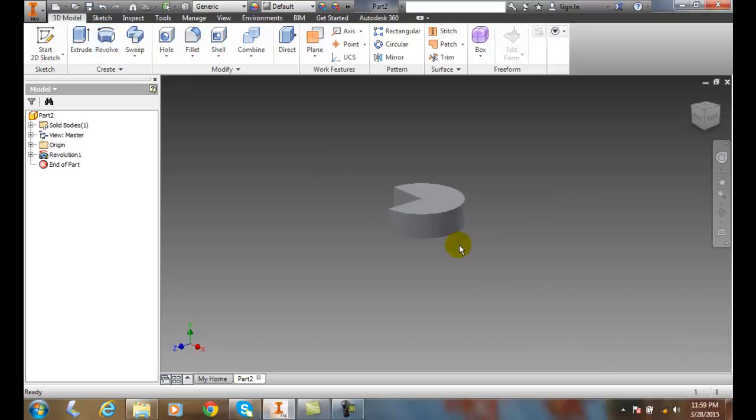So I get a little different options in the revolve versus the extrude, but I can use the direct manipulation of that mini toolbar. So that little mini toolbar has varying options depending on what kind of geometry I get, but lots of people seem to like that.